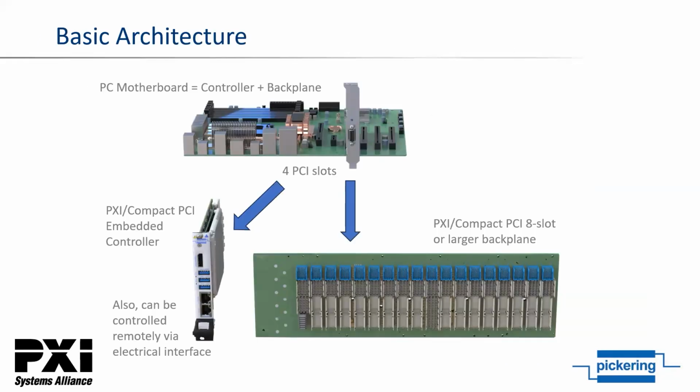Now, this slide shows the basic architecture of PXI. For simplicity, I'm just showing PXI, but PXI Express works on a similar architecture. Like any desktop PC or laptop, you have a motherboard with a CPU, controller, memory, and peripherals. In the case of PXI and PXI Express, the backplane has more peripheral slots, and the CPU and memory controller are modular as well. In this way, you select the best controller for the application, or use an external PC to control the PXI chassis and other peripherals that just don't fit conveniently into the PXI chassis. There are several remote control systems from several members of PXISA that makes this job easy and transparent.